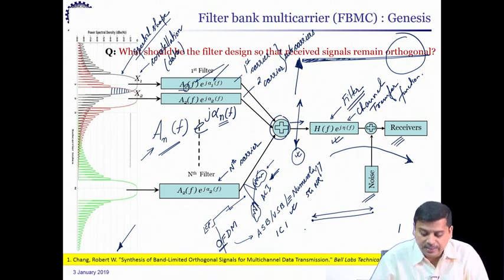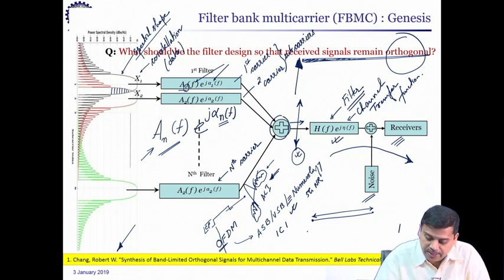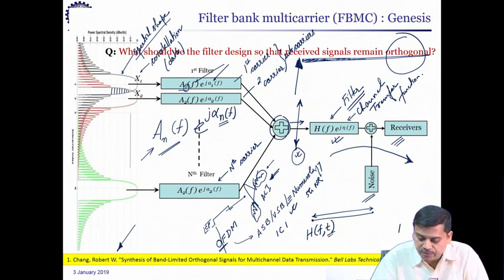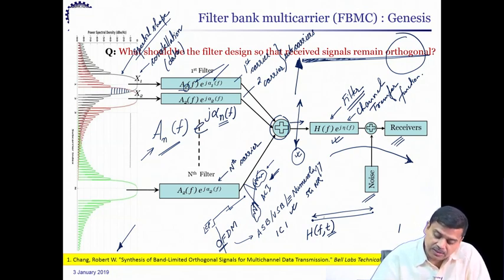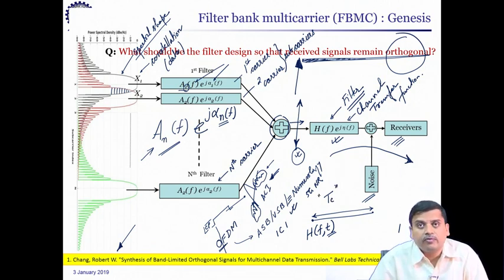In case of wireless links, there is a problem, because this H of f should ideally be written as H of f comma t, which indicates that the channel transfer function fluctuates with time. Hence, these schemes to be realized in their exactness as described just now are valid as long as we maintain the coherence time constraint. We had seen such a constraint earlier when we talked about the link adaptation mechanisms that are typically used.